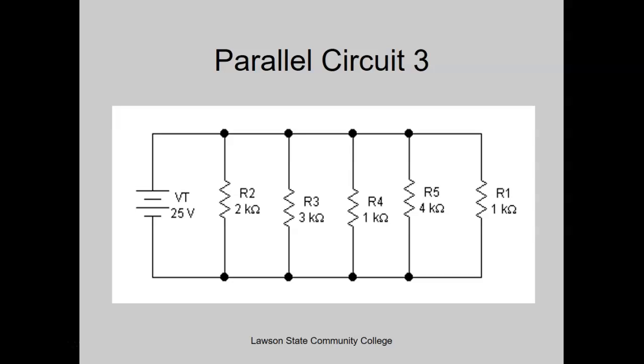All right. Once you find this right here, this is your conductance total, these two numbers, the 0.003083 and the 3.083 millisiemens. That's your total. That's from adding all those.